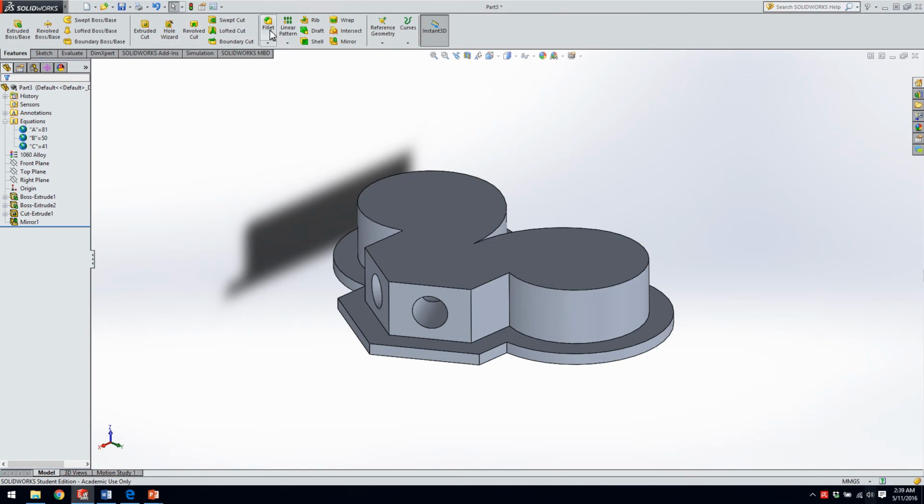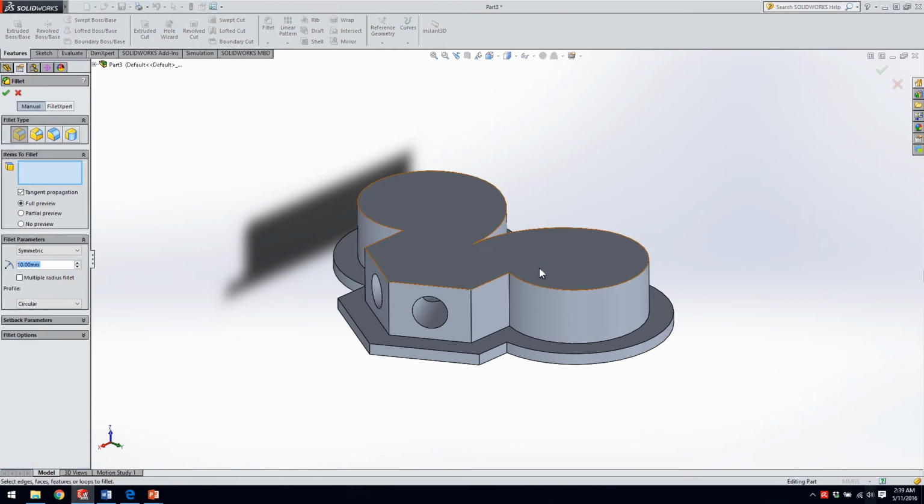Okay, so say I want to add some fillets, which is basically rounding off edges. I can choose an edge that I might like to round off, and I can choose how much to round it off. Or if I just click it, I can also see these icons pop up, which says maybe I want to fillet a lot of things all at the same time.